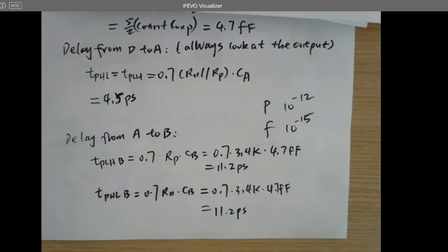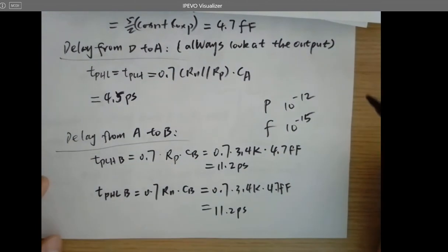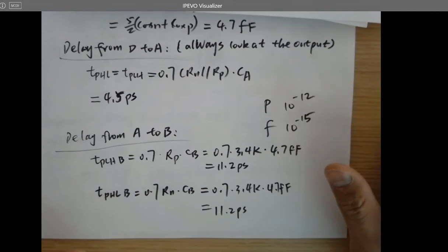Which is great. Whenever you are designing the NMOS and PMOS, you want to make the channel resistance the same. However, the resistivity of the channels is different. That's why we size the dimensions of the PMOS and NMOS differently. Normally we have a larger PMOS and smaller NMOS.